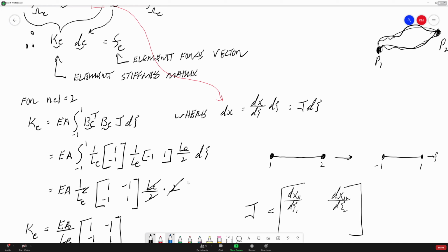It's a change of coordinate systems, going from this element here with a 1, 2 to this other C space where we're saying, okay, when we're over here, we're going to call node 1 -1, and node 2 we're going to call 1. We have these Lagrangian shape functions. Shape function N1 has the value 1 here, and it has to be 0 over here. And then we have this other shape function N2 that represents this side over here to help us with that.